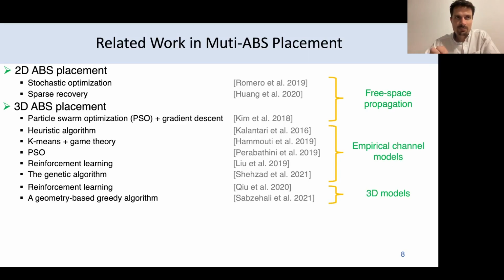These ones use an empirical model which essentially quantifies the attenuation based on the elevation of the link and whether the environment is rural, urban, suburban, whatever. And these ones require 3D models of the environment, a 3D model of all the buildings, trees, cars, obstacles, everything, which is not generally available in practice.